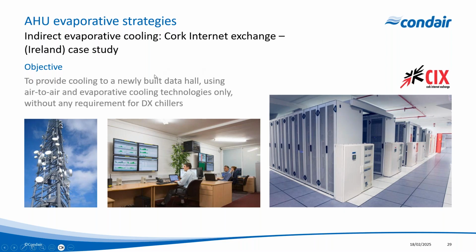So this is a project for the Cork Internet Exchange in Ireland. And the objective here was to provide cooling to a newly built data hall using air-to-air and evaporative cooling technologies only. They did not want to use any DX expansion cooling, so no chillers or mechanical cooling systems with this building. So we worked with the leading air handling unit manufacturer to supply the evaporative systems for this project.